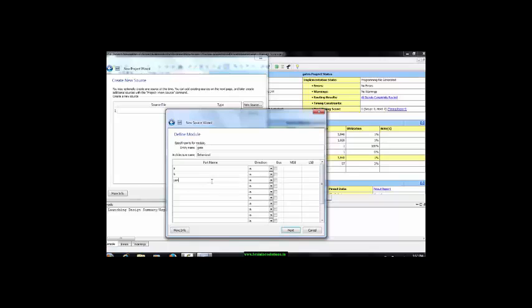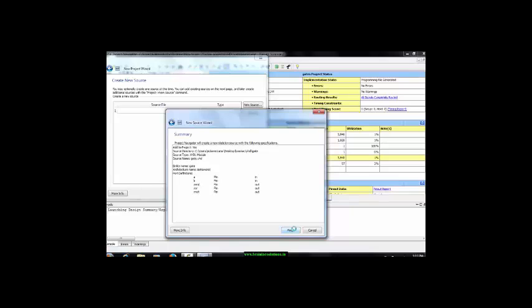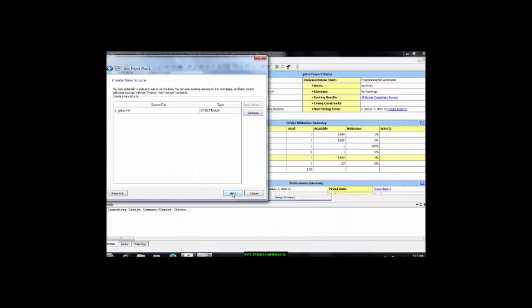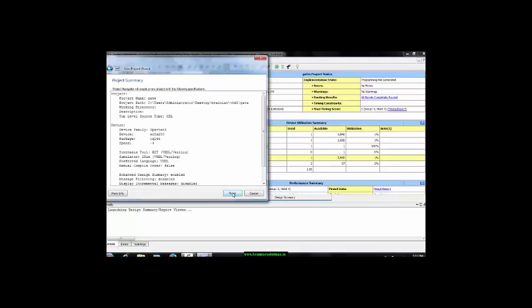Let it be Y and the direction is output, Y or, the direction is output, and Y not, the direction is output again. Press next, finish, then next. Okay, if you want to add any existing sources, you can select this, we don't require that here. Next, and then finish.